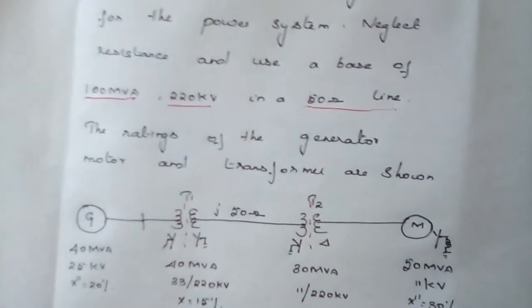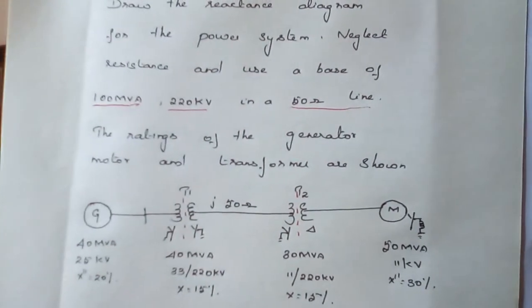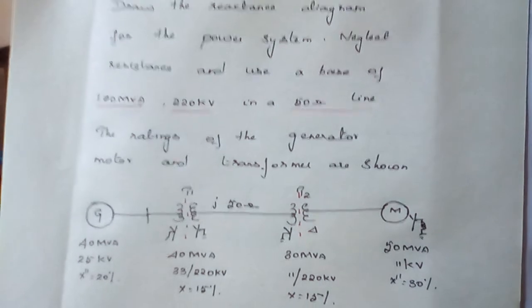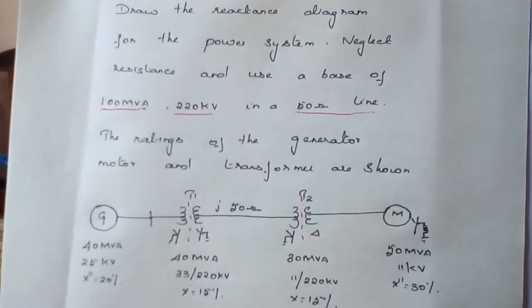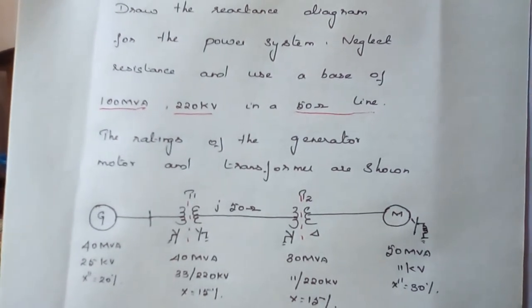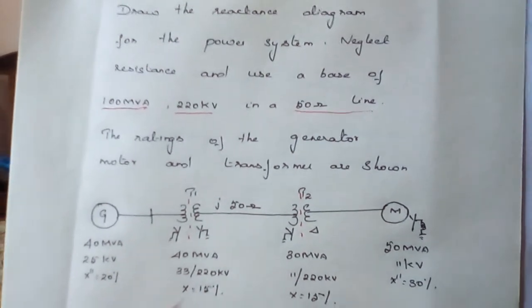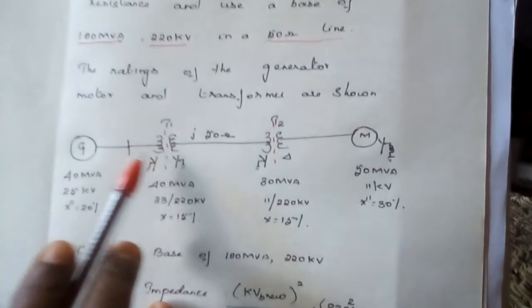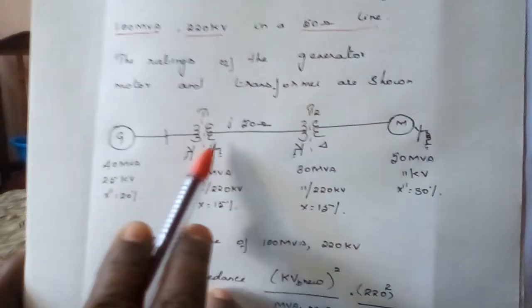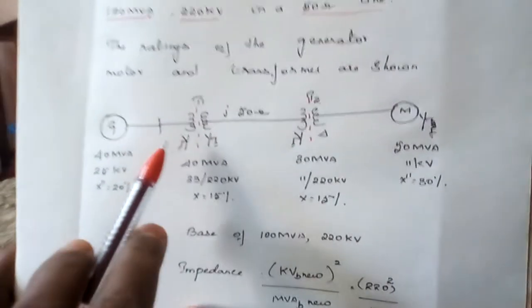Why do we need to sectionalize? Because transformer voltages tend to change, and the voltage changes are caused by the transformation ratio proportions. Due to this we are going to calculate different kV values for each section apart from the component ratings.